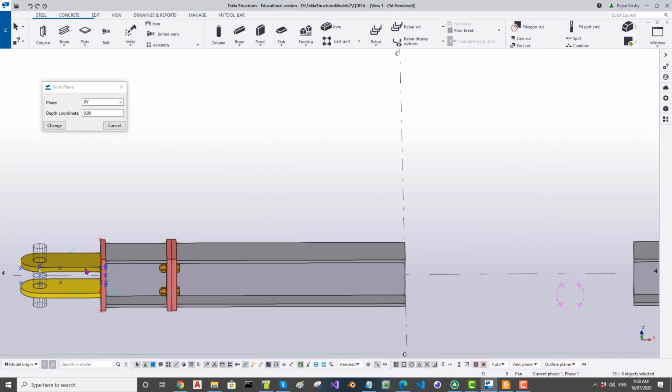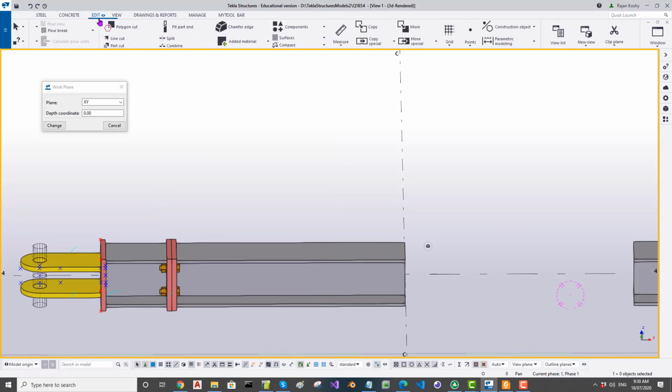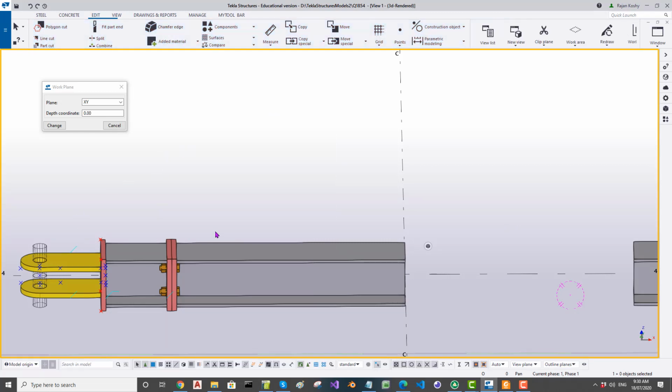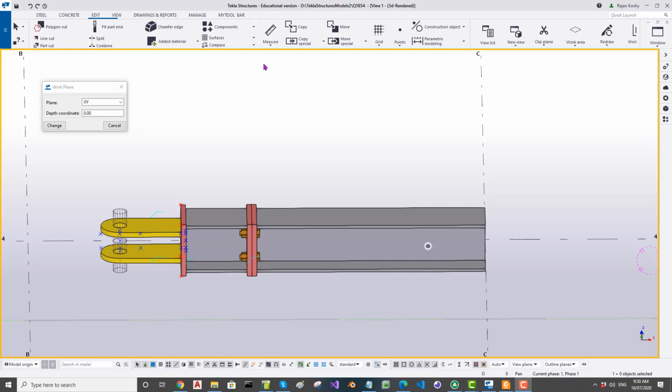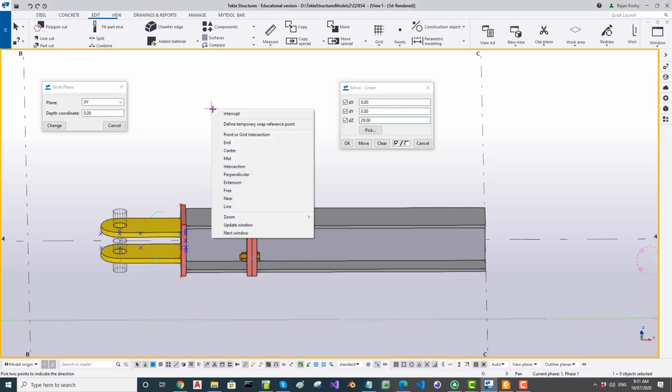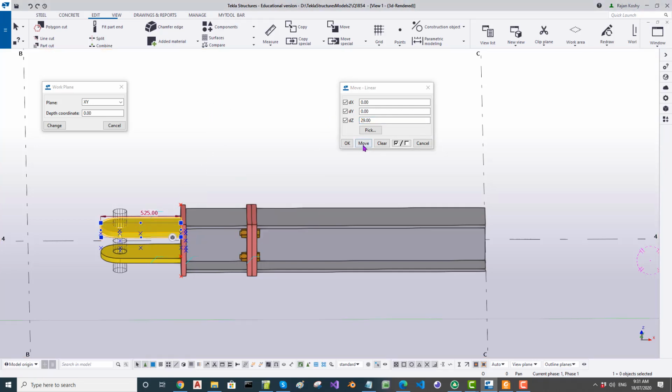So this has to move out a little bit. How much? I calculated that before, which is 29 millimeters. So let me do that. So I go to edit. I should have welded it before. Let's weld it first. No, it was welded. Okay, let me move spatial. Go to move spatial, linear. Clear all of that. How much we had to move? 29. So 29 positive. Let me move that first. Move. And this one will be 29 negative. Minus 29. Move.